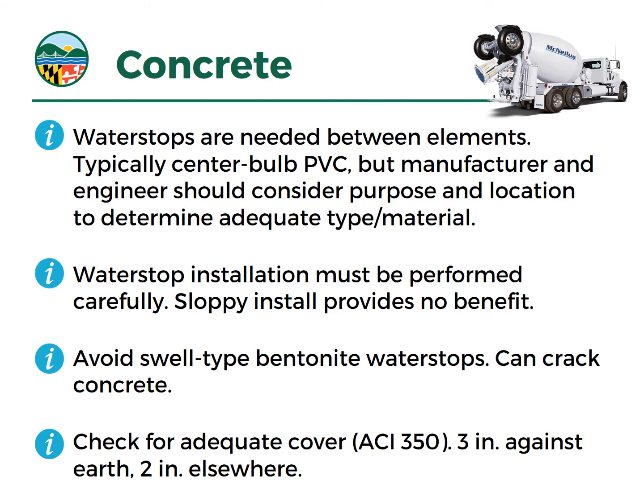We recommend the design of concrete in accordance with ACI 318, which is the normal code for concrete design, but also applying the ACI 350 requirements, I think it's called, for environmental structures, which are slightly more robust requirements to deal with these water-bearing structures that are in harsh environments. And I think any application where you're up against water permanently, like in a dam, would qualify for this. So 3 inches of cover is recommended when you're pouring against earth, and 2 inches elsewhere at a minimum.